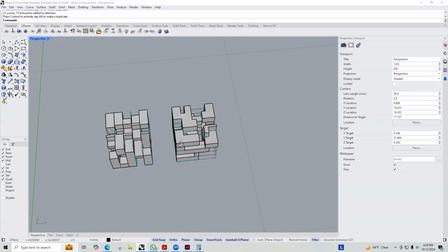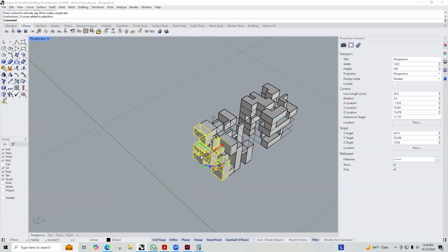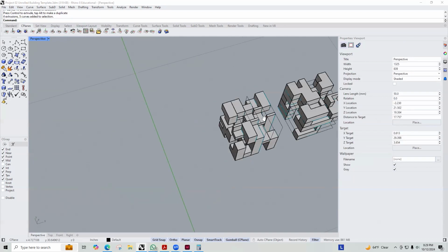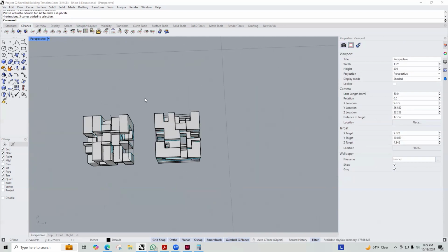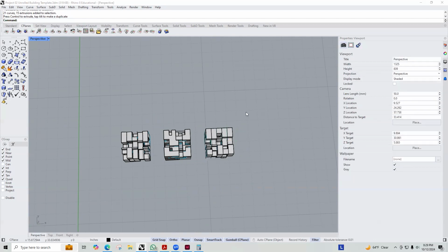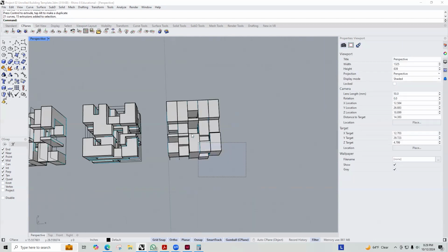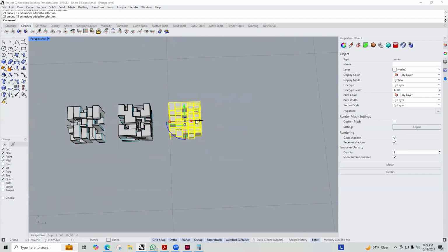So now if this is my front elevation here, I should see that face on this left side, which I do. So that means that it was properly rotated. And we're going to continue that. Instead of -90 here, I'm going to just do regular 90. All right, and then one more.